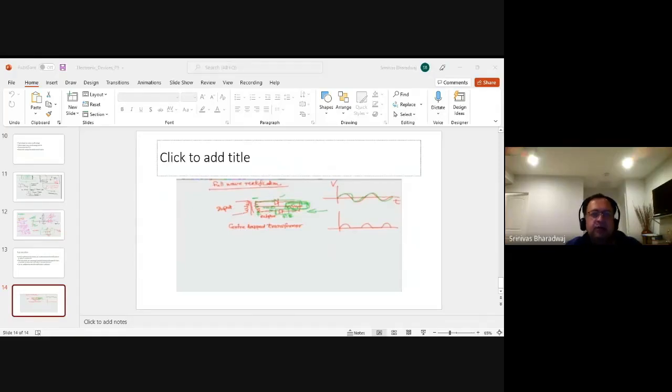Now, as I discussed before in teaching you how those problems work, when the diode acts in forward bias, an ideal diode will act as a short. In reverse bias, it acts as an open. That is the ideal diode, but normally it follows more realistic principles, where the diffusion current and drift current match up.